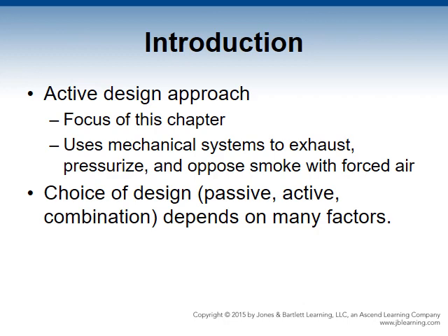An active design approach utilizes mechanical systems to exhaust pressure and, in some situations, oppose smoke with forced air. Most mechanical systems operate when they receive a signal from a fire protection system initiating device that has detected or reacted to a fire condition in the protected structure.